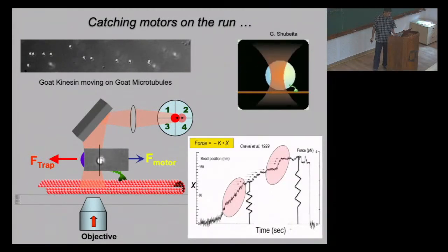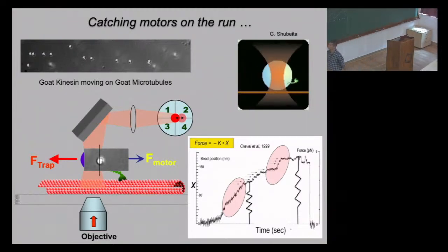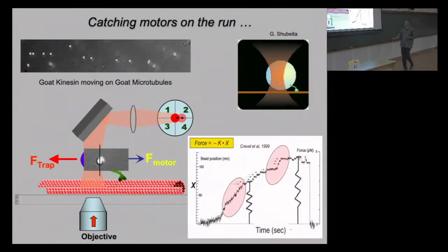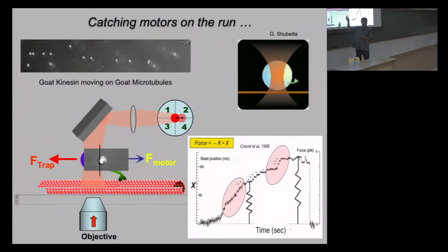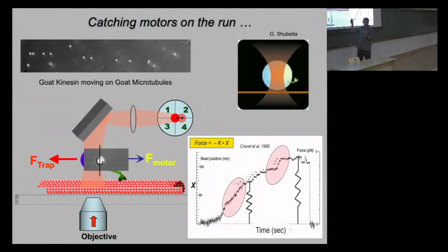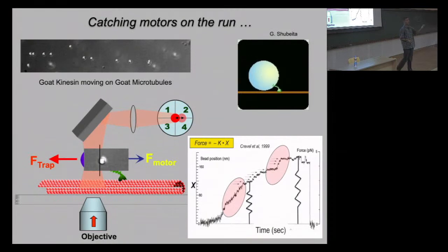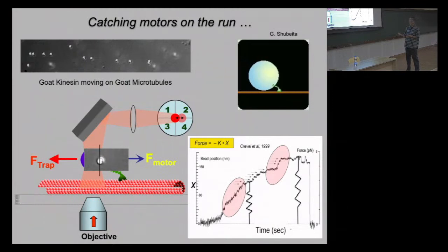As I was explaining earlier, this laser beam gets focused and is then incident on this kind of a detector. This is a quadrant photodetector. It has 4 quadrants, each is a photodiode, and when light is incident, it generates current proportional to the number of photons, to the intensity of light coming onto it. And when this object moves like this, the shadow of this object also moves like this.